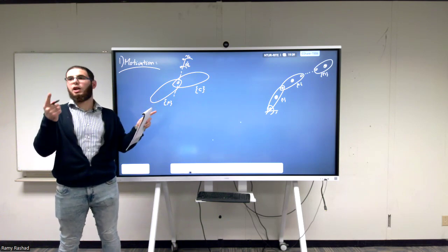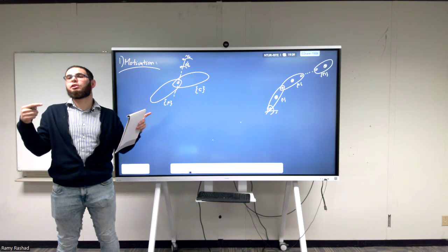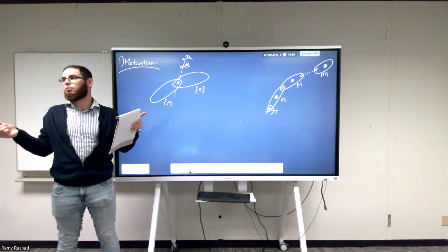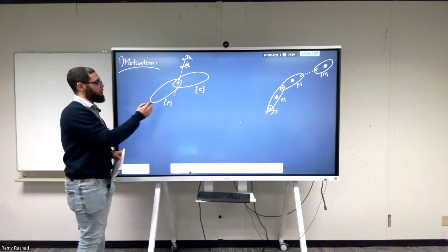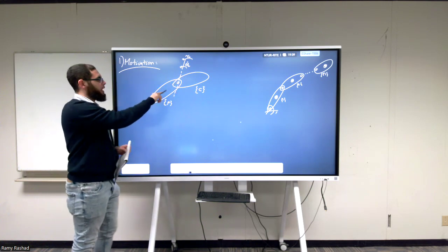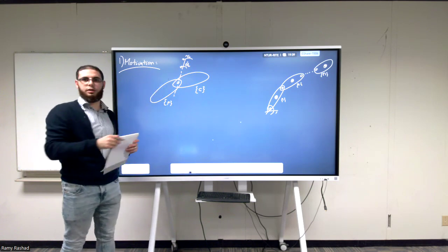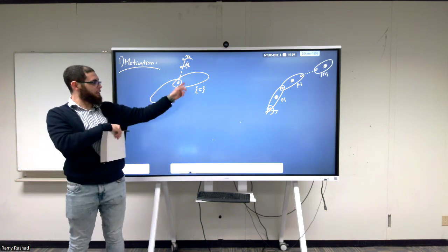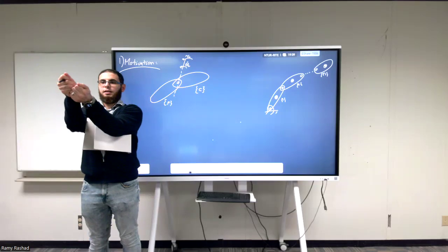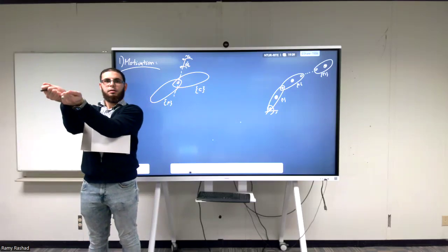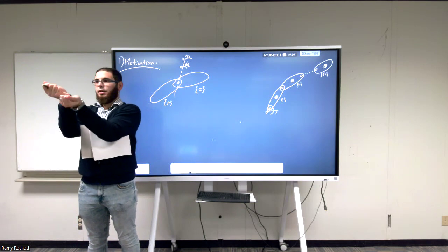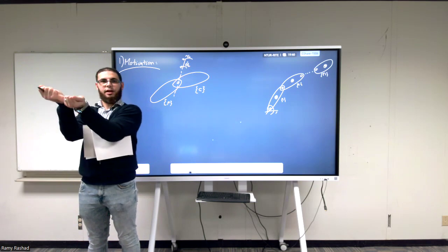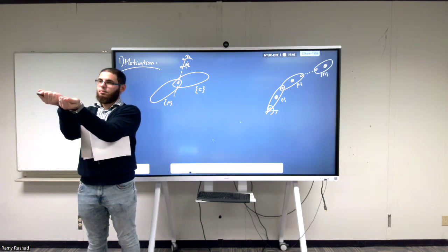If this is a revolute joint, it will have one joint, which means how many degrees of freedom did it constrain? 5, right? So it constrained 5. I'll give you an example. If we say that this is a revolute joint and it is connected in this way between these two rigid bodies, this means that these two rigid bodies can rotate like this with respect to each other. You agree? This means that they're not allowed to move relative in this direction, also in that direction. What's the third one? Also in this direction. So these are 3. And it's also not allowed to rotate like this.